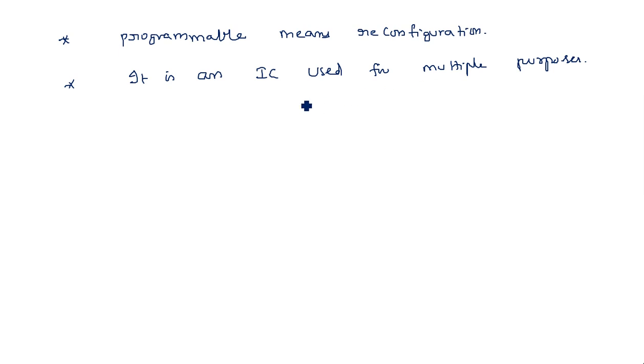So a lot of advantages are there. Inside the PLDs we have fuses, and they will be blown depending upon the connection and the disconnection. I will tell about that when we go into the designing of the PLDs. PLDs include ROM, PLA, PAL, PROM, EPROM; like that we have different logic types involved in the PLDs. All these combined are known as programmable logic devices.